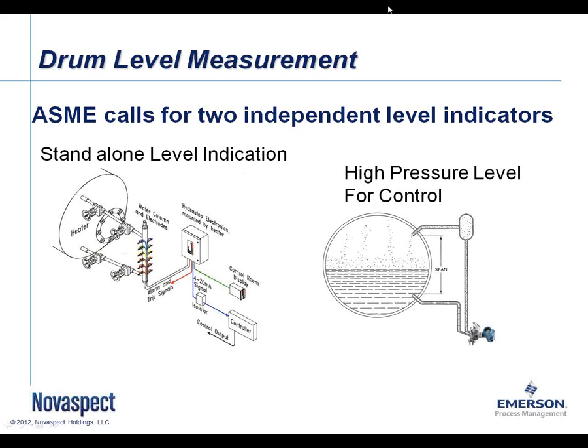The other application that we're showing here on this page on the right side is a fairly typical installation for differential pressure level measurement. Some of the key issues here are that the calibration of that transmitter cannot be merely the span value of the distance between the two sensing taps. Because this environment right here is saturated steam, completely blanketed, and this is saturated water, we have a difference in density here than we would if this was air and just water. Therefore, we have to adjust our calibration here or compensate online continuously for the changes in density.